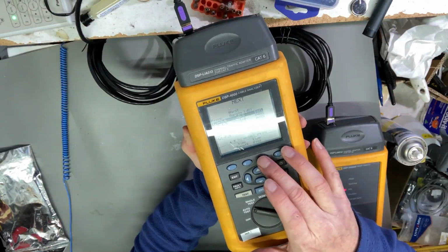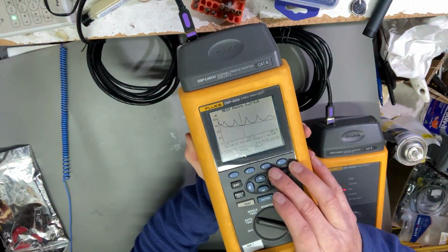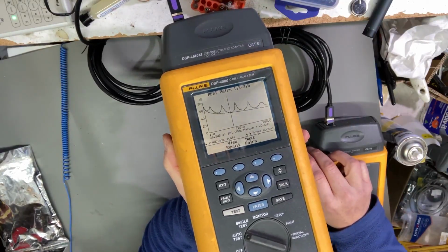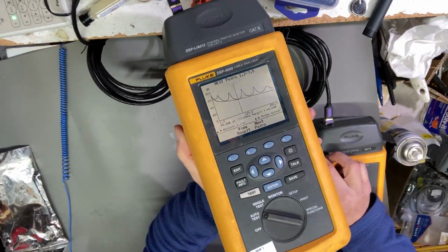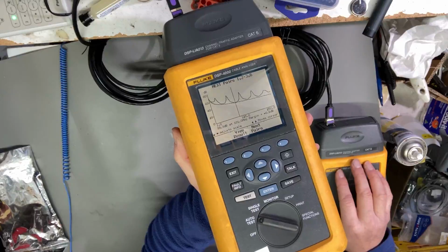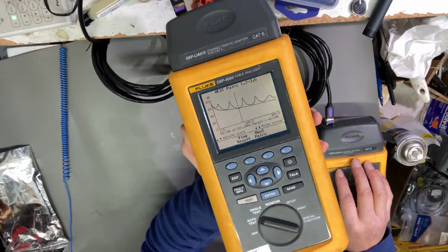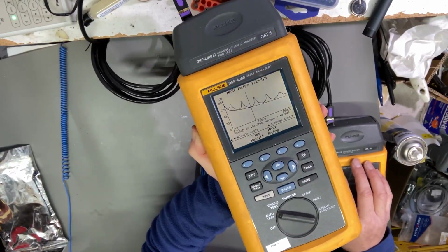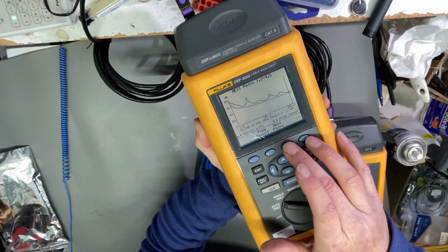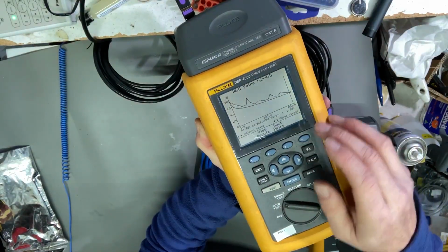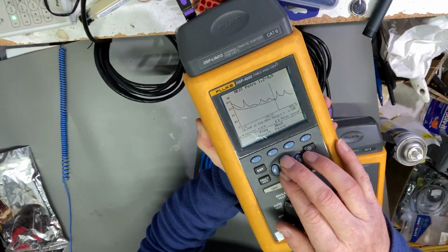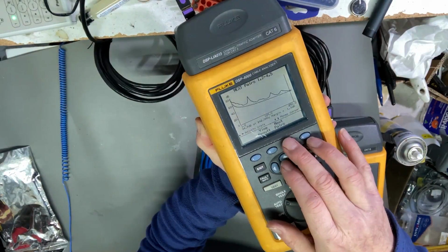If we go into the view plot here for these different pairs, the smooth line at the bottom is the test standard, and the wavy line is indicating how that cable measured, and if it goes below that line at any point along that frequency, then it's a fail. And look at the next pairs as well. So it's checking all combinations of pairs. You can see right at the end here, we can actually zoom in on that as well.